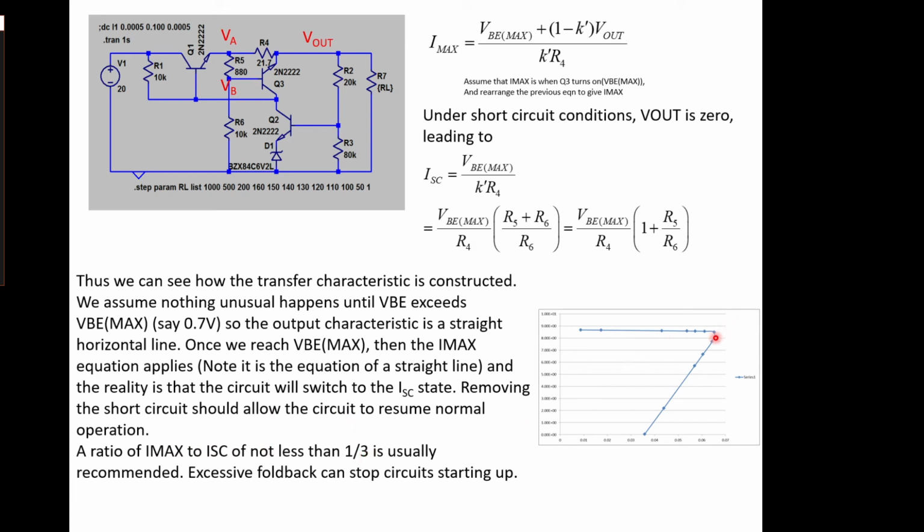If you make this too steep coming back down here, you can actually have trouble turning certain circuits on, because when circuits turn on, particularly inductive circuits, there tends to be an inrush of current, and if your inrush of current exceeds this point here, then it assumes a short circuit and switches straight away. So we have to make sure that you give it a bit of headroom for startup conditions. You don't want your fold-back circuit stopping your circuit from actually turning on under normal conditions. So that's just something to watch.